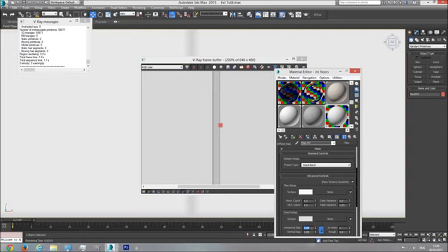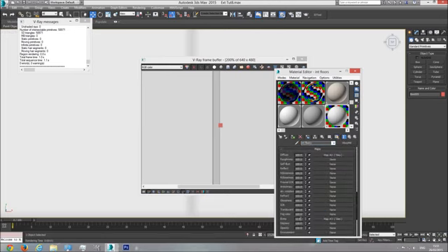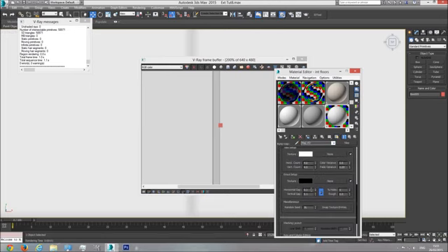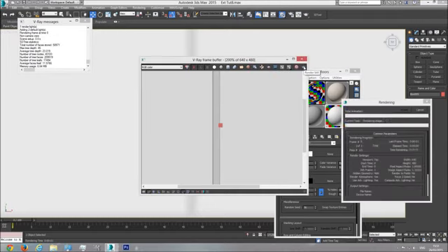In most situations it's supposed to be locked to be the same, because you don't need a different width of separation for the horizontal and vertical. So 0.08, and then I'm going to go to the bump, and same thing here, horizontal gap 0.08. And let's try rendering now.